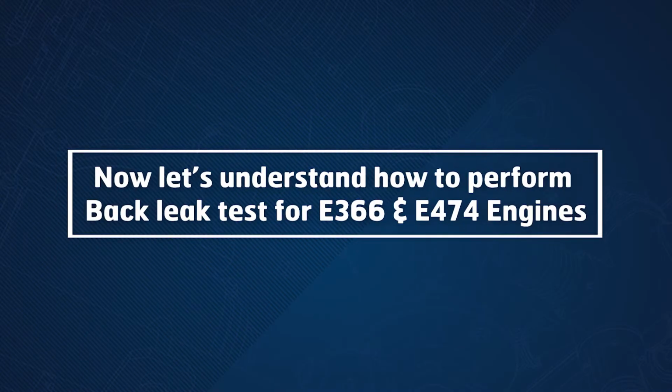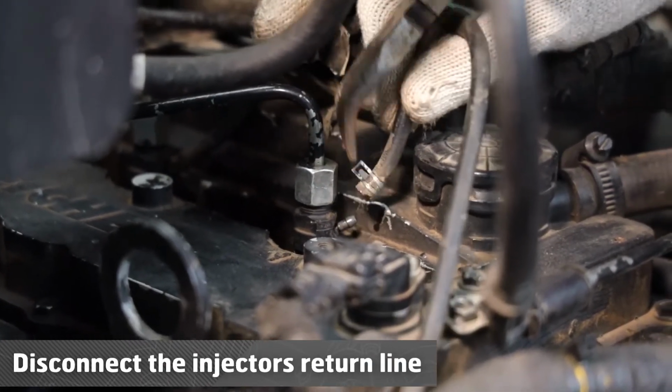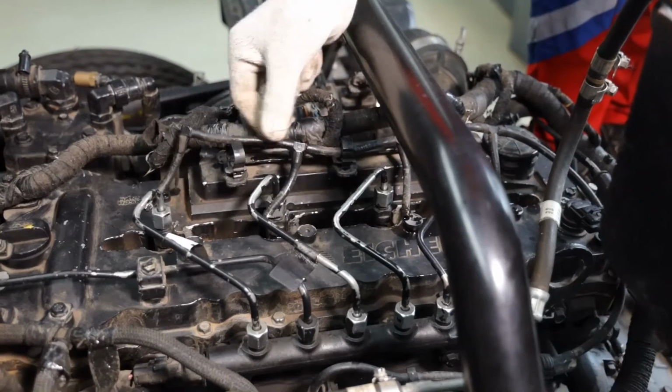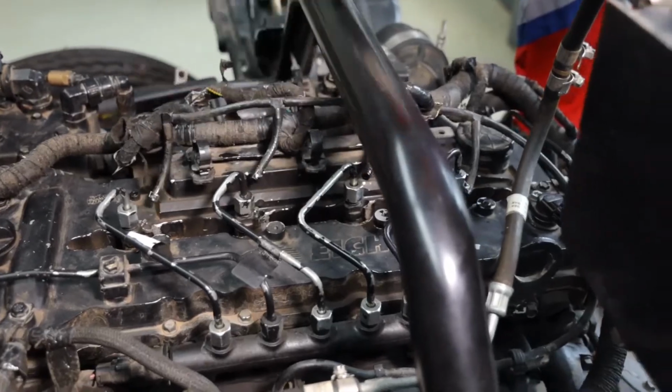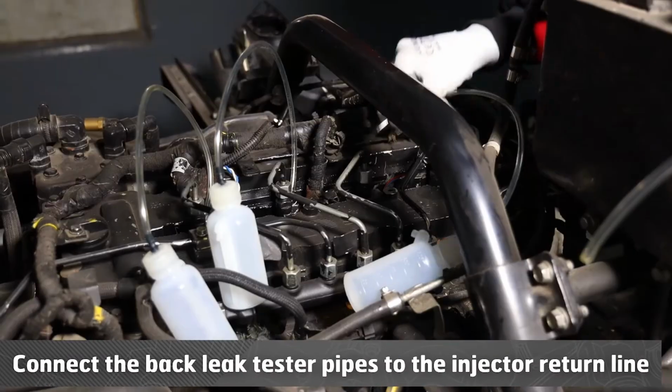Now, let's understand how to perform back leak test for E366 and E474 engines. Disconnect the injector's return line. Connect the back leak tester pipes to the injector return line.